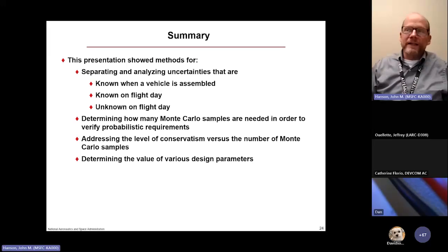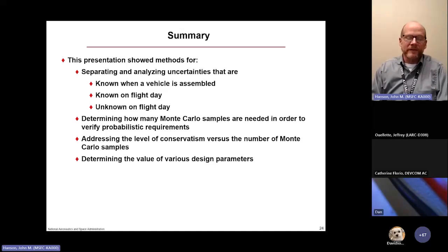I don't think I can give you that answer to apply to everything. Yes, we typically use 90% vehicle models, and then we'll run 3 sigma flight day variations. Because once we launch, the things that go into that 90% model, you'll know on flight day. And if you found that you had a 97% case when you only really designed to a 90% case, well, you haven't launched it yet. So maybe you swap engines out and use stronger engines or something. You haven't risked it yet at that point. But once you launch it, it's got to get to where it's going. So we will typically use 3 sigma for that.